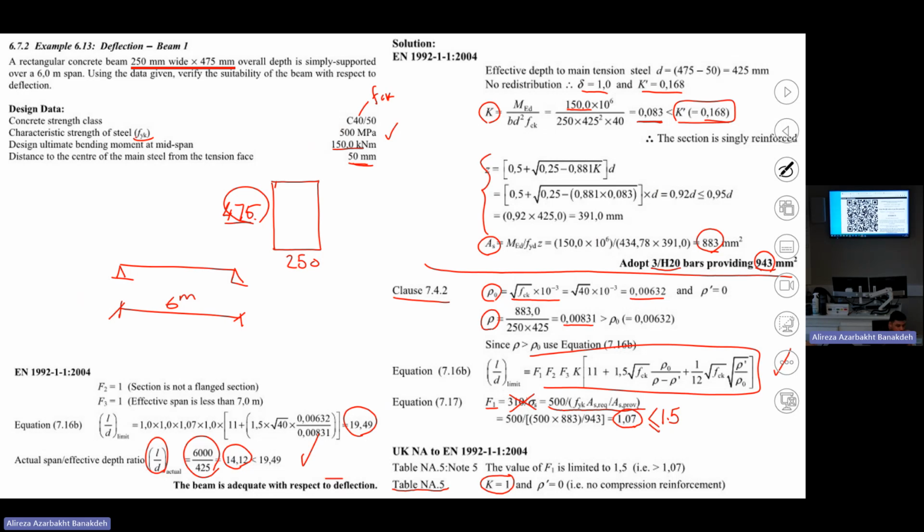Maximum length of the same beam could run up to 8,000 millimeters. But if it was 8,000, the thing would have changed, right? Yeah, F2 would have changed. And then again we are into a problem. So we have to again change F2 and check the number.